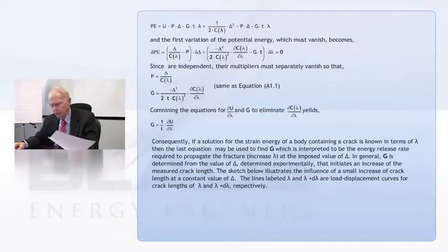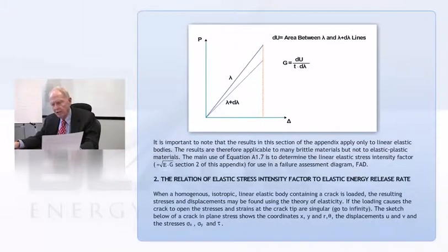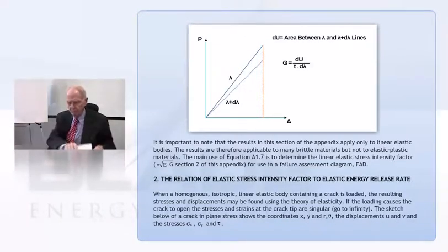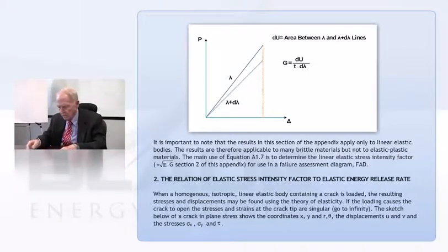And there's a little curve demonstrating how, as the crack length changes, the slope of the response curve, the P versus delta, changes, and that the area between the two divided by the change in crack length is related to the energy release rate. So if you like to look at derivations and listen to stories, that's good. What I just said is obviously not going to apply to a plastic material.